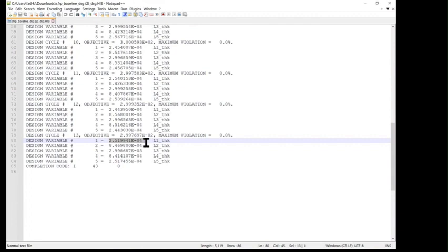And if we divide that by 0.2 times 10 to the minus 3, because that's the thickness of each ply, that suggests that we've got 1.2599705 plies at that orientation. And remember, that was our minus 90 layer. Minus 90, minus 45, 0, 45, 90. So that suggests that we've got just over 1 1/4 plies at minus 90 degrees.